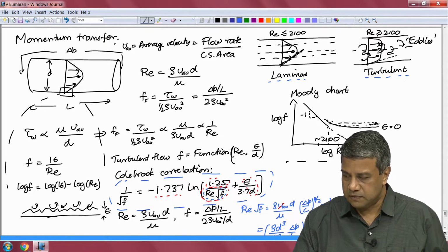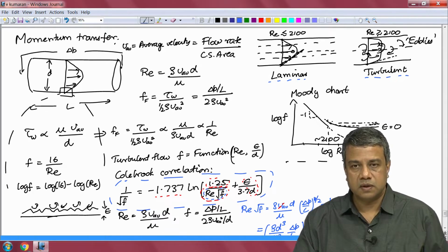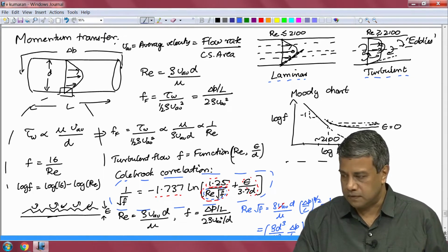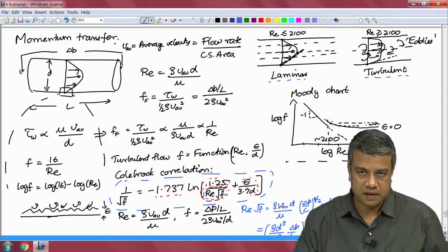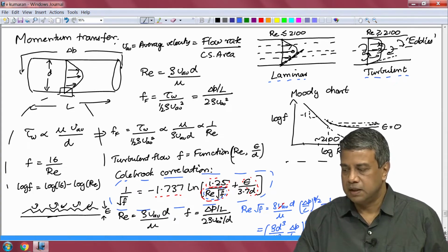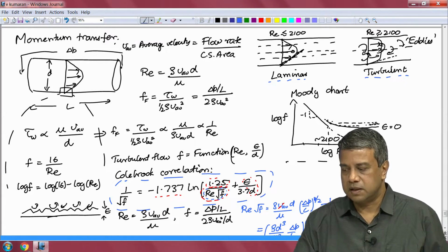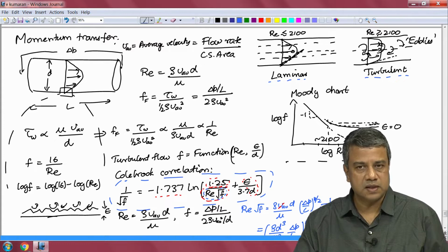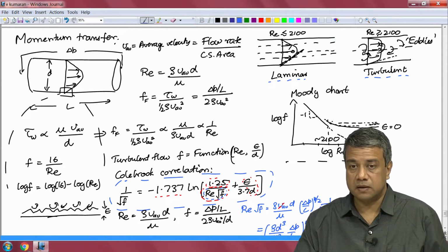At a Reynolds number of about 2100, there is a spontaneous transition to what is called a turbulent flow. In a turbulent flow, the velocity profile is flatter at the center and the velocity increases more steeply at the wall in comparison to a laminar flow. The streamlines are no longer smooth and steady. There are large velocity fluctuations perpendicular to the average flow.